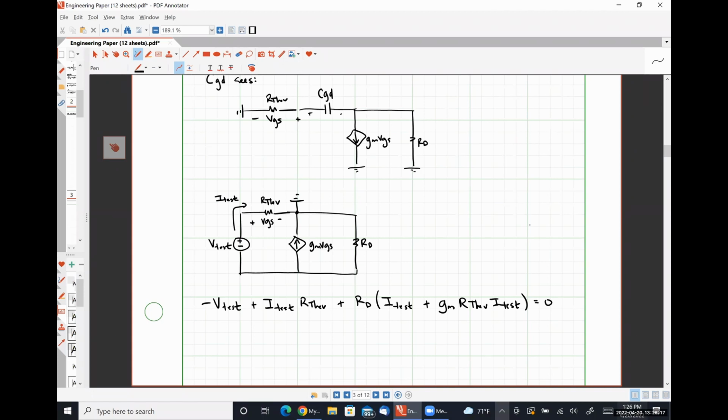No, and I definitely understand that. So having that labeled as ground right there, maybe doing KVL around the loop as I've done previously, might not be the best analysis method to use. Nodal analysis or perhaps mesh analysis might be a better way to explain what's going on, wherein I won't have to worry about that ground.